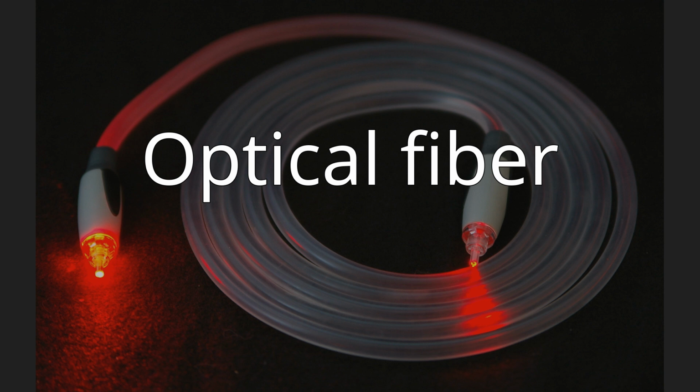Specially designed fibers are also used for a variety of other applications, some of them being fiber-optic sensors and fiber lasers. Optical fibers typically include a core surrounded by a transparent cladding material with a lower index of refraction. Light is kept in the core by the phenomenon of total internal reflection, which causes the fiber to act as a waveguide. Fibers that support many propagation paths or transverse modes are called multi-mode fibers, while those that support a single mode are called single-mode fibers (SMF).